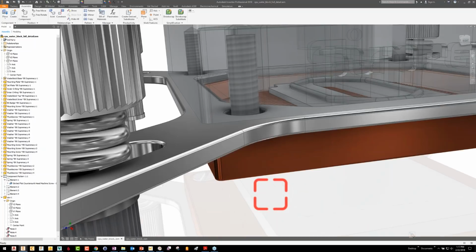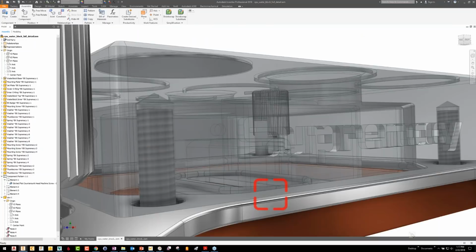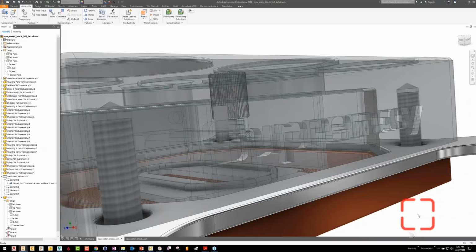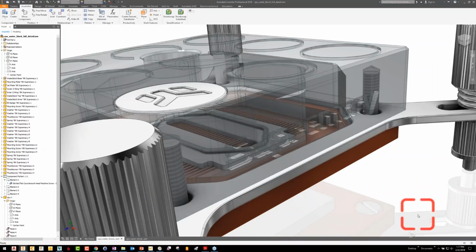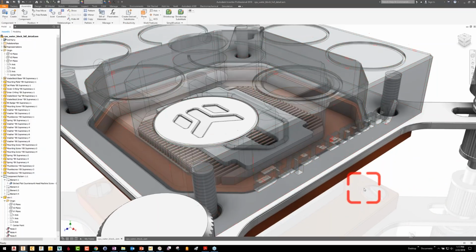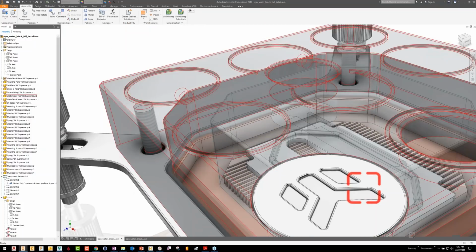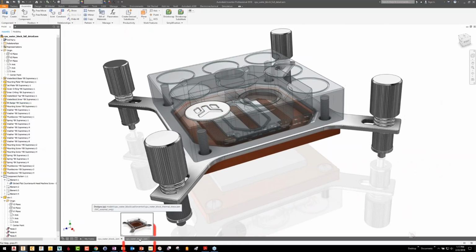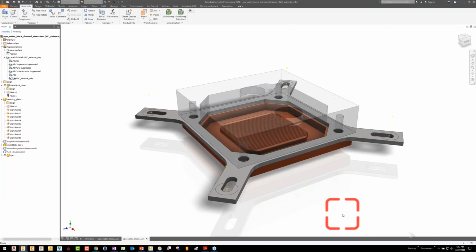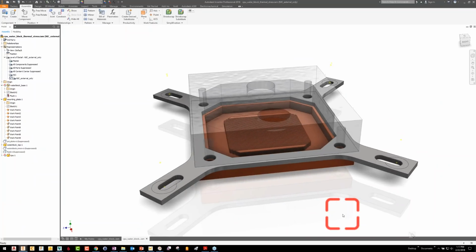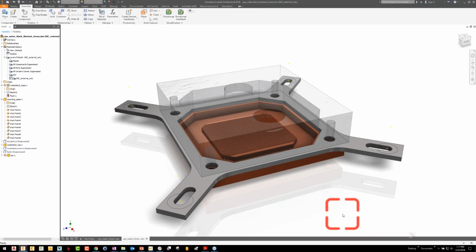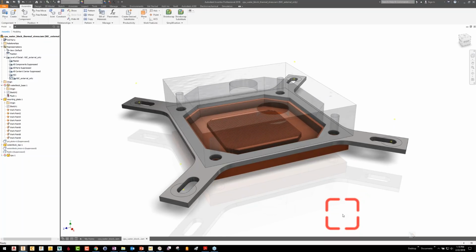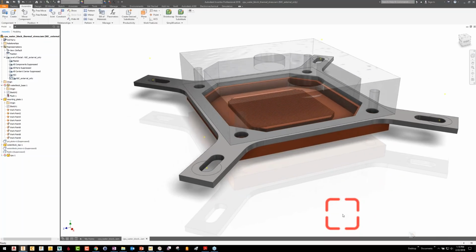Lots of little fillets and chamfers, decorative features like the company logo cut in the side, a little decorative badge on the top, little grooves that are just for looks. Get rid of that stuff. You know, it's just going to cost you unnecessarily. And that's what you'll see in the stripped down model that's been provided. Unnecessary parts, unnecessary features are removed, and in some cases, features added. And you'll see why as I go to set things up.